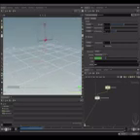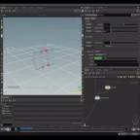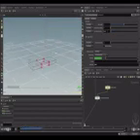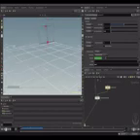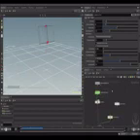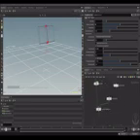Then if I change this value to, for example, 0.1, you can see the force is weak this time. But as I say, this is sub-step dependent. So if I go to the rigid body solver and change the number of sub-steps to 50, this is going to add this operation 50 times on each sub-step.